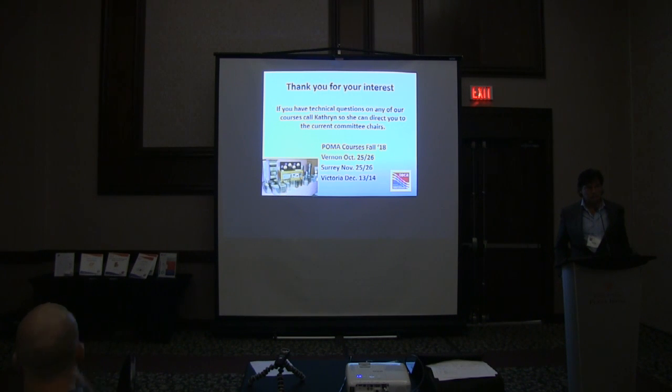Dave, what I see in the field is 1 inch ceiling filters with no MERV rating on them. What would you guess them to be? Sorry, say the question again, please, Doug. Out in the field, I've seen a lot of 1 inch filters that are pleated, but they have no MERV rating on them. I'm just wondering what would you guess them to be? I'm guessing 6 or 8.